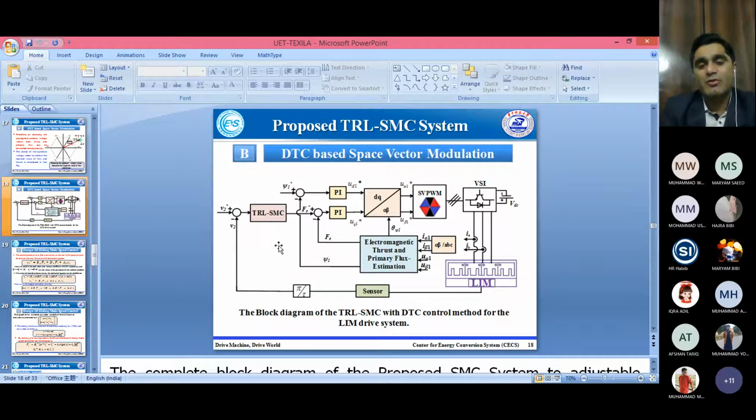For example, we want to operate the metro line or subway or any train or electric vehicle at 1000 RPM. So we give the reference speed over here. And we can calculate what the feedback, meaning the output speed, would be: the same 1000 or somehow smaller than 1000. Then we compare both speeds over here, and after comparison there would be the error.